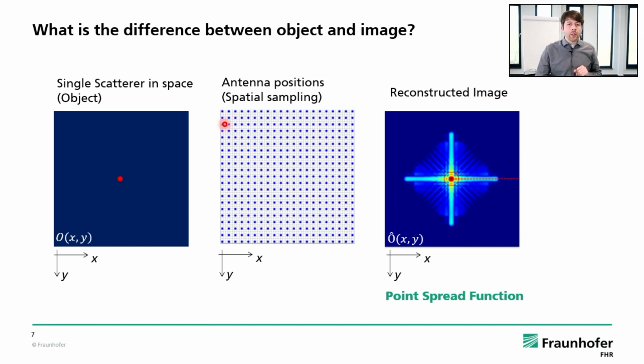So we take a set of antennas. We could, for example, take a rectangular grid, one after the other, over the XY plane, just over an entire aperture. We are sampling the signal and measuring from each point. And then we are adding up over all antennas. Of course, it's focusing just to the maximum where the object is. So the image has the highest amplitude where the object was. Otherwise, we wouldn't get the representation.